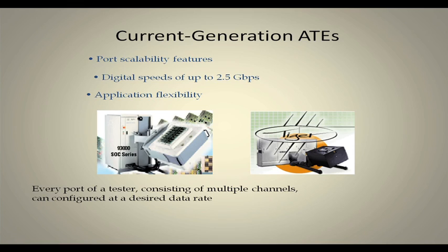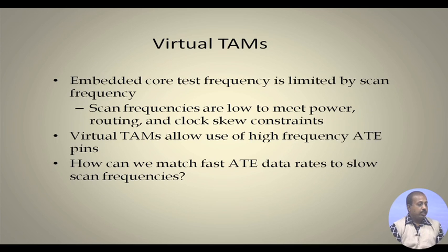Okay. So that way we can think about different modifications to the basic test scheduling that we have done using bin packing or using partitioning, so that it can take help of these tester features. The first one in that category is known as virtual TAM, the virtual test access mechanism. As the name virtual means, actually the TAM lines are not more, but it gives an illusion that the TAM lines have been increased.